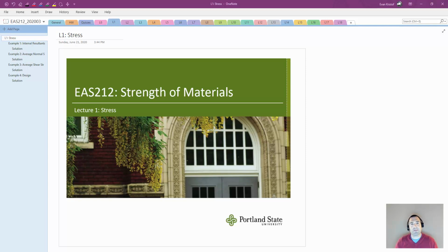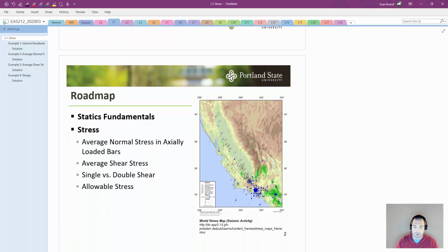And then that allows us to estimate the change in, let's say, the deflection of a beam due to a given loading. Once we're able to relate the stress, the intensity of the loading at specific points of a member, to the strain, which is the change in geometry at the same point, then we use calculus to integrate, and that makes life a little bit easier. So let's go ahead and introduce this concept of stress.